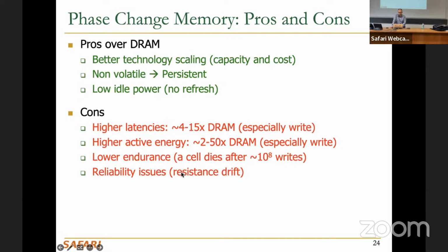So we don't, for example, have issues like RowHammer, with this read disturbance, but you have similar other issues here in PCM: accessing your PCM at some point can cause some resistance shift. So your resistance window can shift. And if you don't update your references, you're going to read wrongly. And that's also the case for flash memory. And that's why we always need to update our reference voltage for flash memory as well.